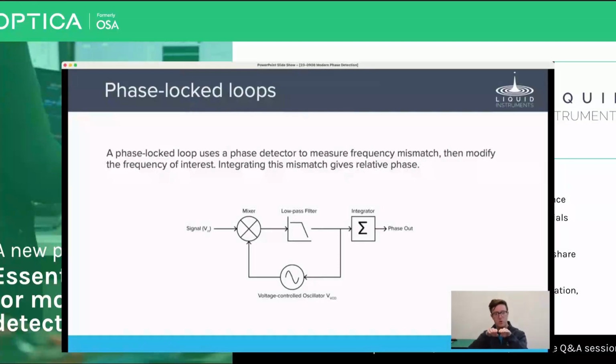And it'll keep moving towards the input signal until the output of the phase detector of the single phase lock-in amplifier starts to stay steady. So in this way, as the input signal changes, the voltage controlled oscillator frequency also changes, and the two chase each other around. They're locked together. They're locked to the same frequency as each other. That's the locked bit of a phase lock loop.